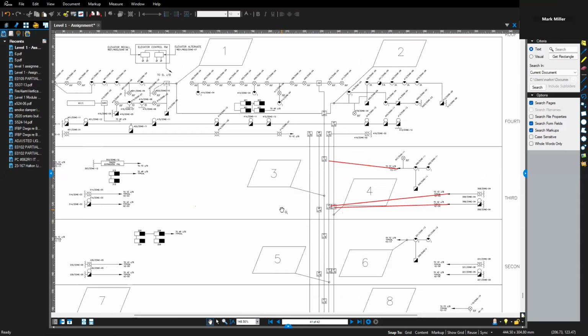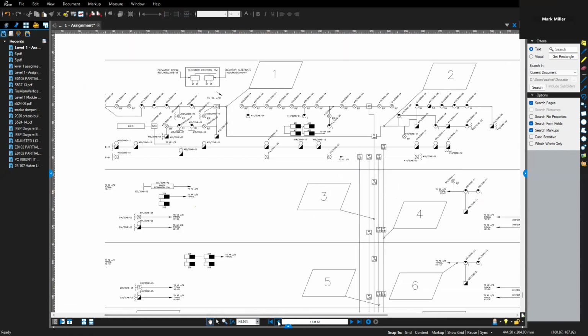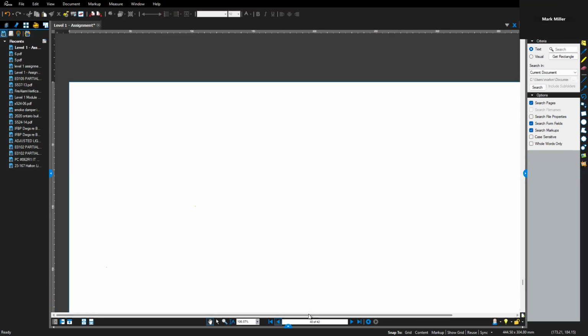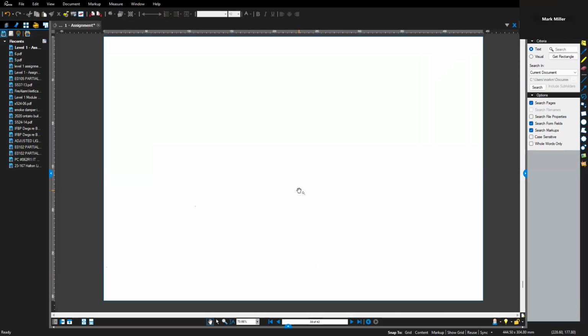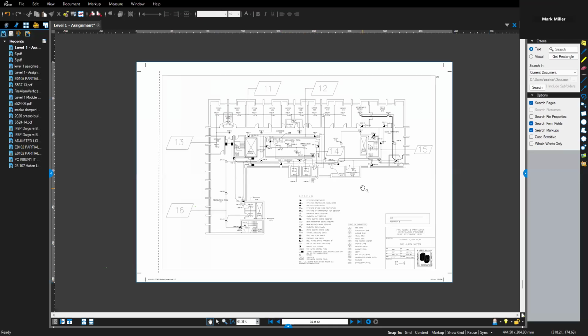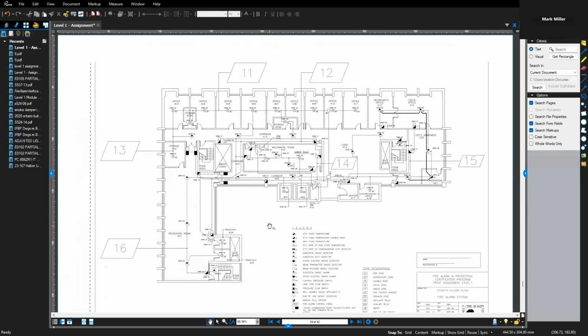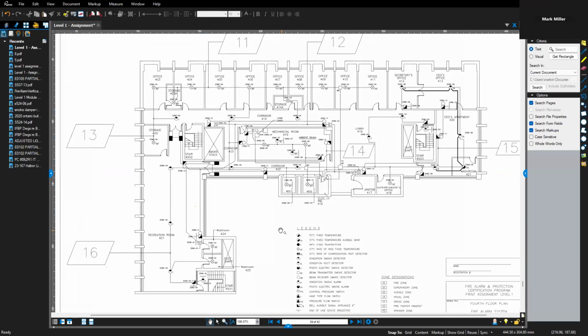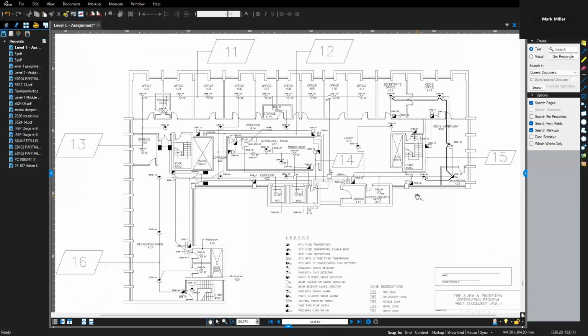There's things missing because it looks like we don't even have the contract for the first, second, and third floor. We're just doing the fourth floor. So that's fine. We'll concentrate on the fourth floor. If we look at the fourth floor, the building is a little bit odd. If it's an office building, obviously, look, office, office, office, office. It's an office building, which would make it a group D major occupancy, business and personal services.